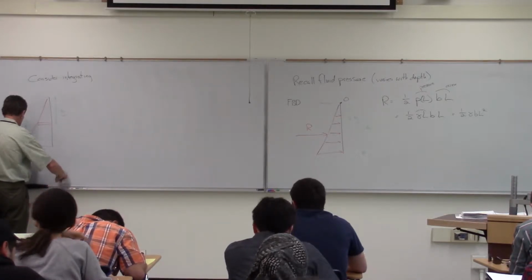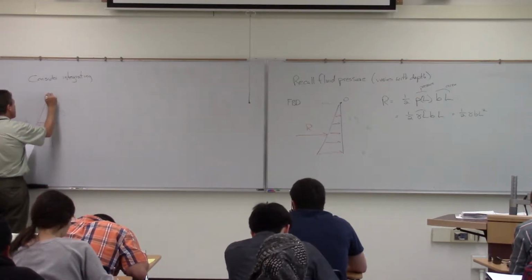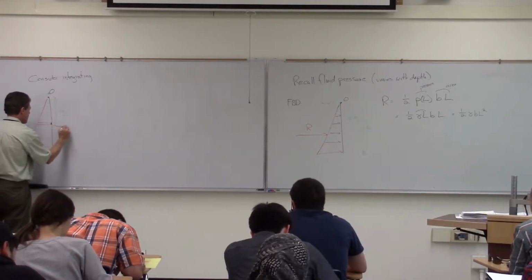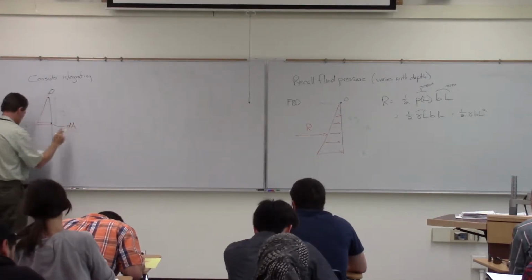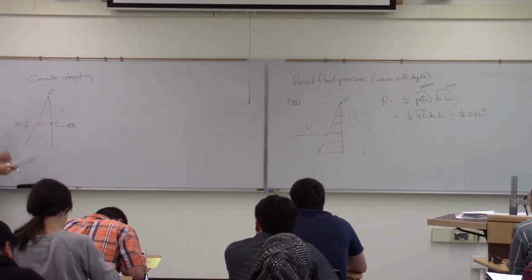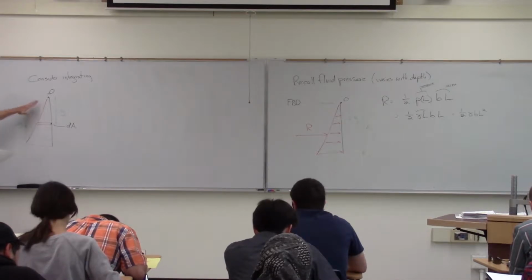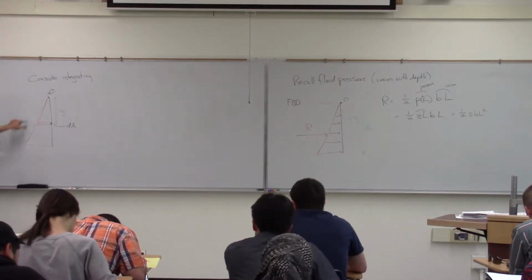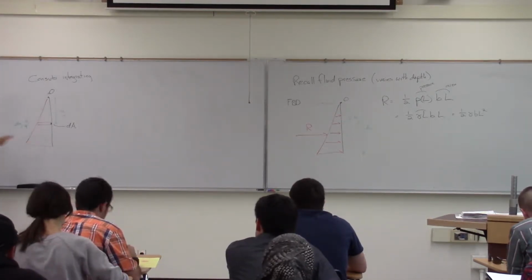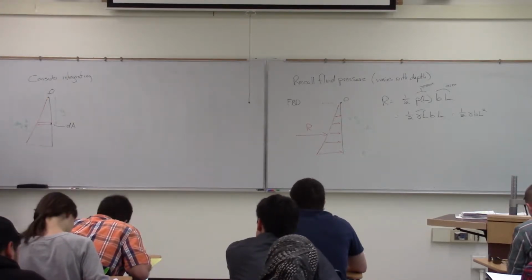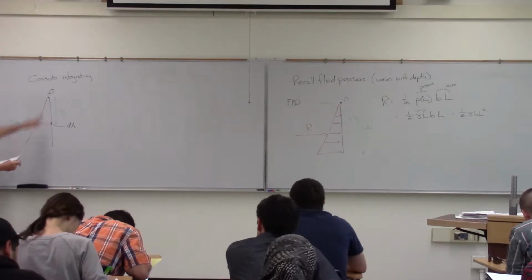Let's see. What we're going to do is take a horizontal strip of dy, go down from dy and calculate this same equivalent force. So basically all we're going to do is just integrate that. We're going to calculate that area under that curve there.